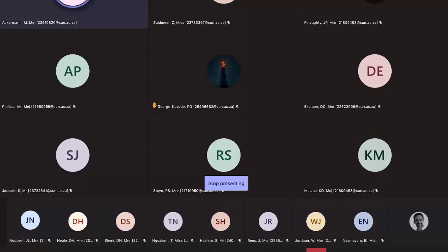So there will be a clock cycle in between the two transmissions, because it goes back into the idle state, and only then does it start transmitting again. But when you set the start TX high, the start bit is immediately sent. Sorry, I'm just thinking, give me a second. So it loads it in the idle state, goes into that state. Yeah, there should be a clock cycle delay between them.